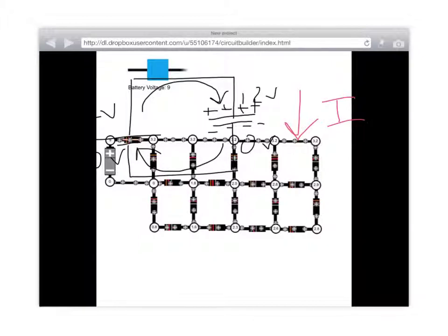Okay, so to finish this up, key idea with capacitors. A capacitor is going to charge until it's charged, at which point we say the current has stopped. So basically, when you initially start charging that capacitor, it just goes like crazy, right? So when you initially start charging, an uncharged capacitor looks like a wire.